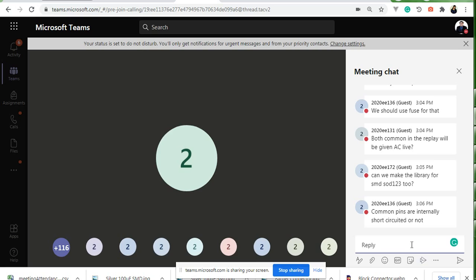And secondly, they have other problems of haphazard tracks, because I have approved them, but yes, there are still some problems in your PCBs, such as haphazard tracks, where there is a straight line and then a little fuzzy line again. Whenever you are making a PCB and such a thing happens, and then that PCB goes inside the acid, the ferric chloride solution, it will be eroded off from that haphazard point. So this is very important.